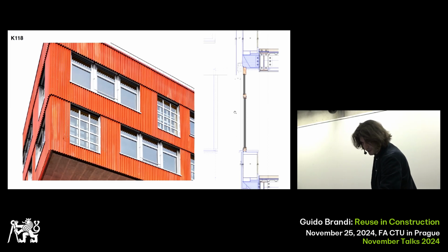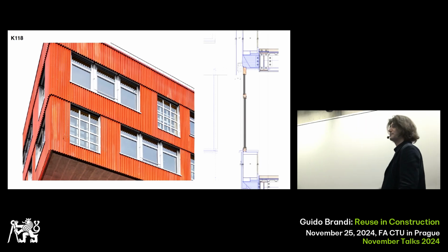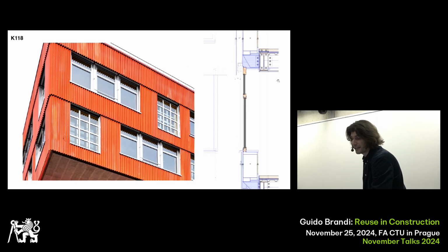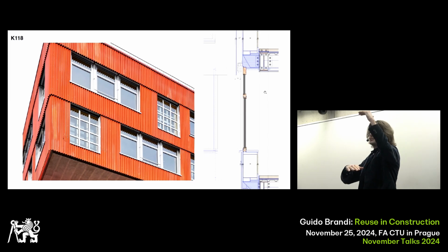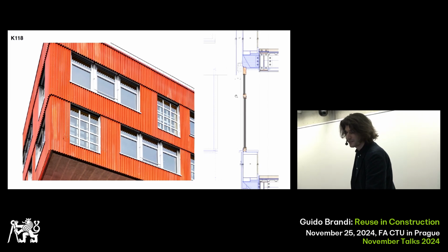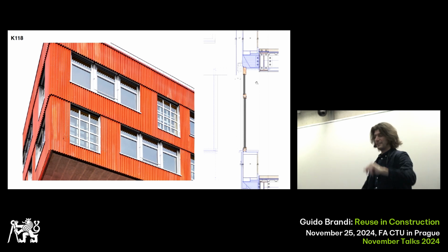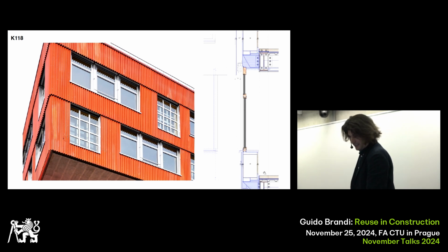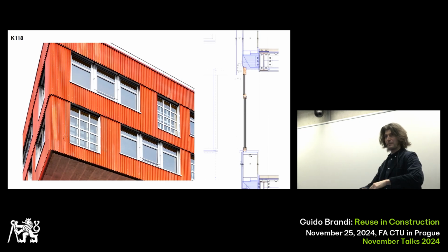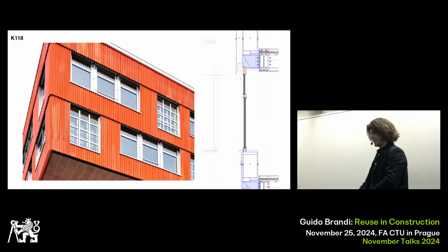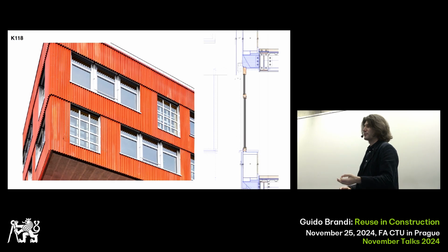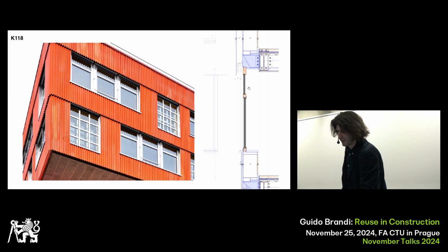And coming back to the windows, this is also an interesting moment. You see, for example, those are the windows from office building Orion, and you realize that you have a steel structure with a given height. You have windows that you find somewhere else with a given height. Then you have the height of the Brüstung in German, the parapet height of the windows, that you have to follow, kind of norms, now 1 meter. And so then you have to place all together.